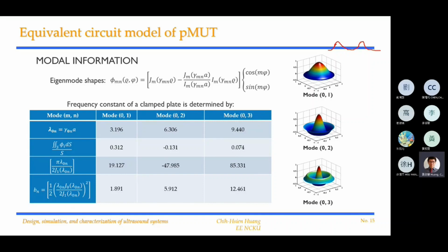So the pressure output here will cancel itself through interference. The acoustic pressure from these other modes will be comparatively very weak compared to mode 01, 02, and 03. So sometimes if people just briefly say mode 1, mode 2, mode 3, you can think of it as mode 01, 02, and 03.